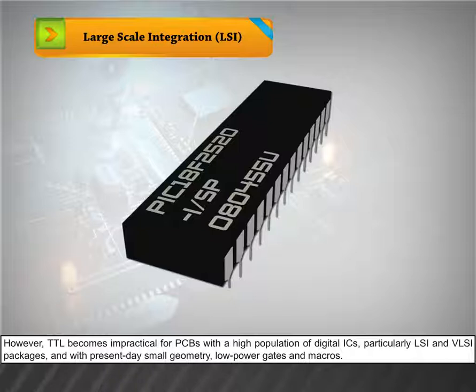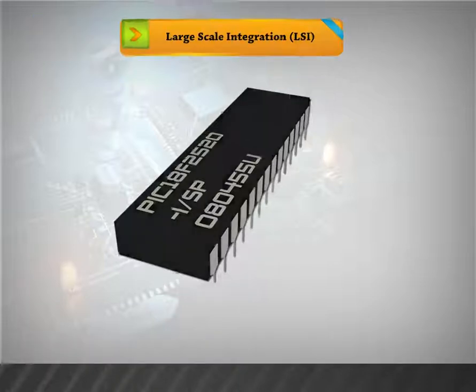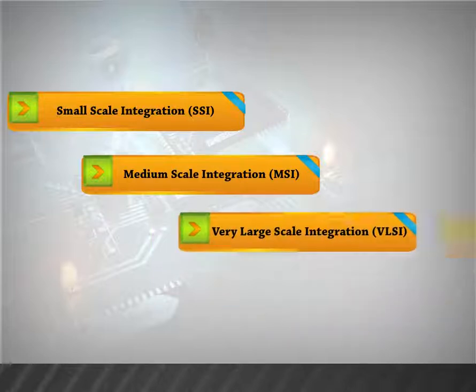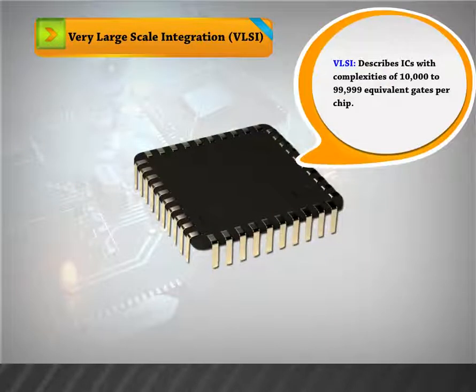However, TTL becomes impractical for PCBs with a high population of digital ICs, particularly LSI and VLSI packages, and with present-day small geometry, low power gates, and macros. Very large-scale integration (VLSI) describes integrated circuits with complexities of 10,000 to 99,999 equivalent gates per chip.